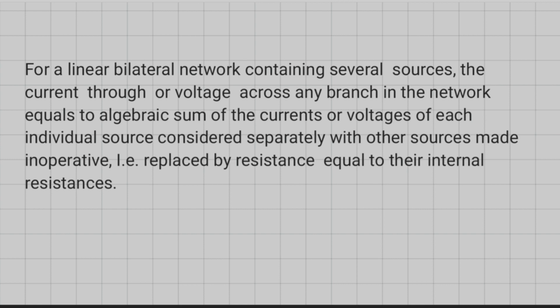In this, if there are several sources, we only consider one source at a time, and when one source is considered, the other source is made inoperative, that is by putting the resistance equal to their internal resistance.